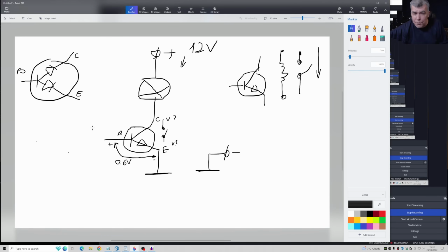Let's come with an adjustable resistor, like that. One end of the adjustable resistor we connect to the plus, and the other end of the adjustable resistor we connect to minus. You see, that's the reason I told you to always read a schematic from the plus, because on the plus you have fewer connections compared to the ground. Just thinking, okay, my voltage is going here and it's going here, will mess up your brain. Always from plus.